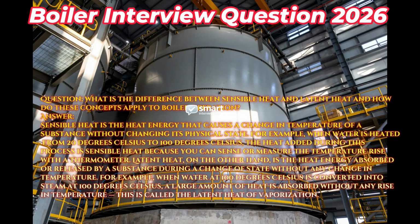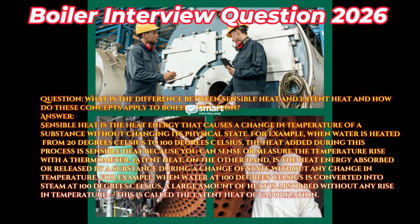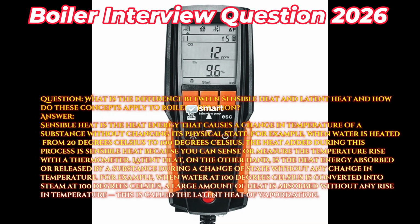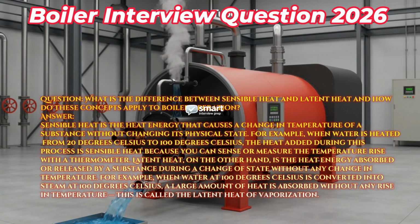Question: What is the difference between sensible heat and latent heat, and how do these concepts apply to boiler operation? Answer: Sensible heat is the heat energy that causes a change in temperature of a substance without changing its physical state. For example, when water is heated from 20 degrees Celsius to 100 degrees Celsius, the heat added during this process is sensible heat because you can sense or measure the temperature rise with a thermometer.